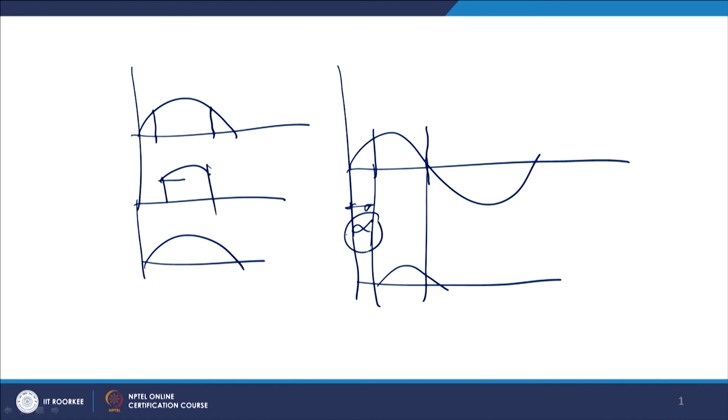And in between, if you require, we will discuss selective harmonic elimination and all those things that can be achieved here. But in case of the thyristor, you can only control alpha, thus you can control only one angle. So, you can eliminate only one harmonic, that will come later.